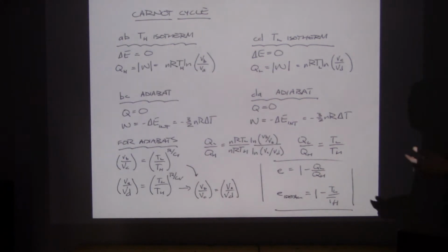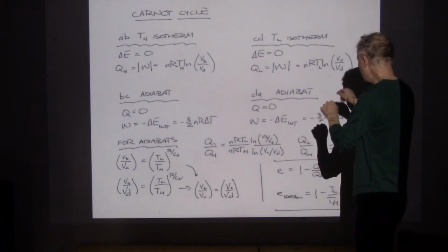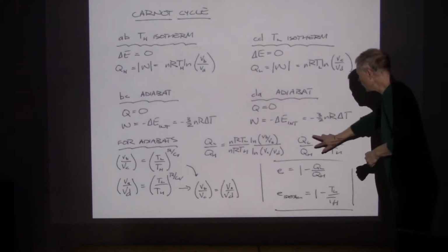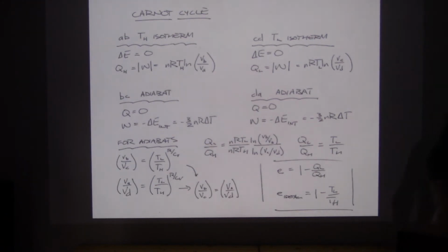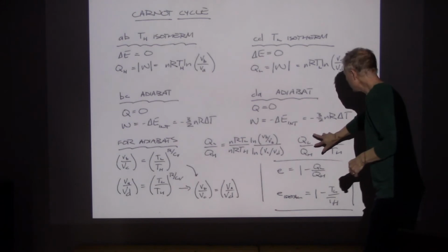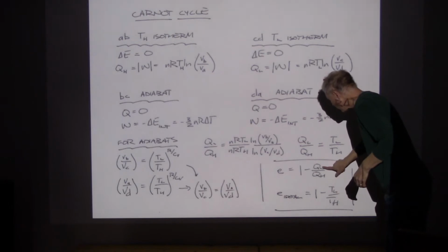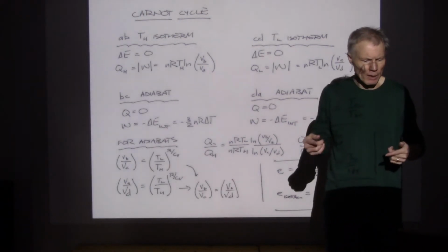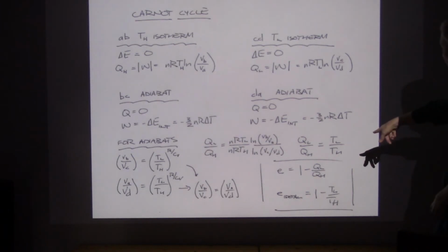It's going to be the same, and so this part cancels out. And it says, for a Carnot cycle operating under these conditions, the ratio of Q's matches the ratio of temperatures. That's what the second law said, that under ideal conditions, the ratio of the Q's will match the ratio of temperatures. So our prediction here is for a Carnot engine. A Carnot engine would be operating at the ideal conditions, at an efficiency of 1 minus TL over TH.